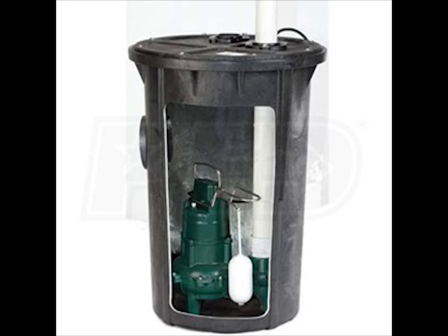There are 2 options on pumps, a grinder pump or a sewage pump. Generally, folks just need a sewage pump. A grinder pump has a large cutter wheel on the bottom and a smaller outlet, and is meant for high head applications. It is 4 times more expensive than a sewage pump. Blades will dull with bad things going through them, it is prone to clogging with stringy materials, and it lasts less long than a sewage pump. Flushable wipes will clog a sewage pump, but will go through a grinder pump no problem.